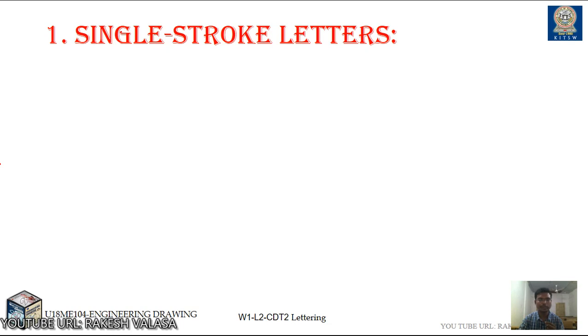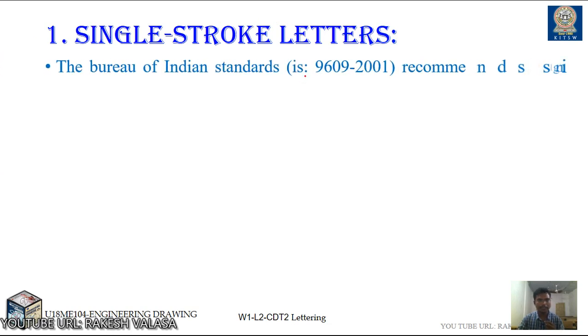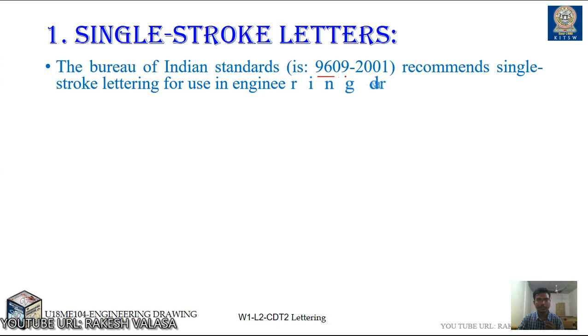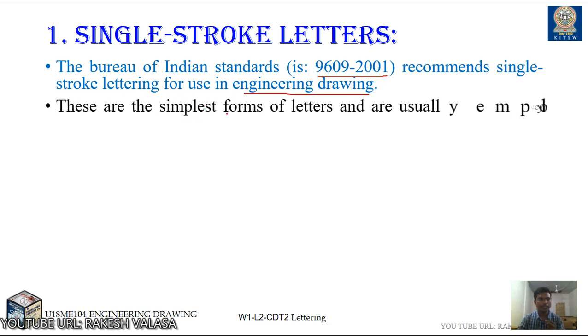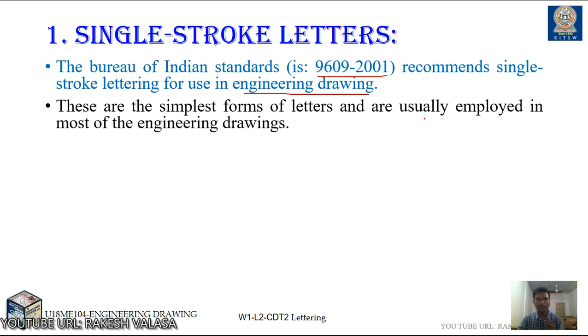Let us discuss the first one, that is single stroke letters. The Bureau of Indian Standards, 9609-2001, recommends single stroke lettering for use in engineering drawing. These are the simplest forms of letters and are usually employed in most engineering drawings.